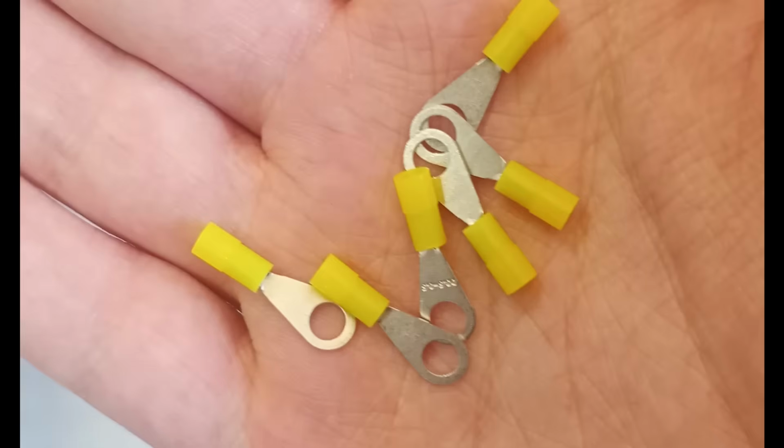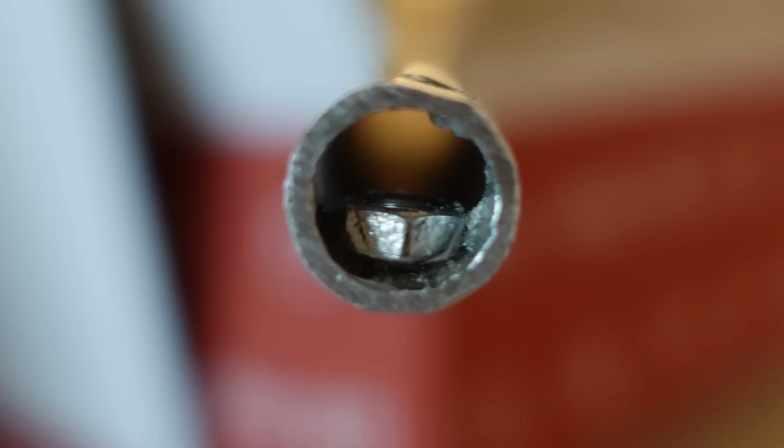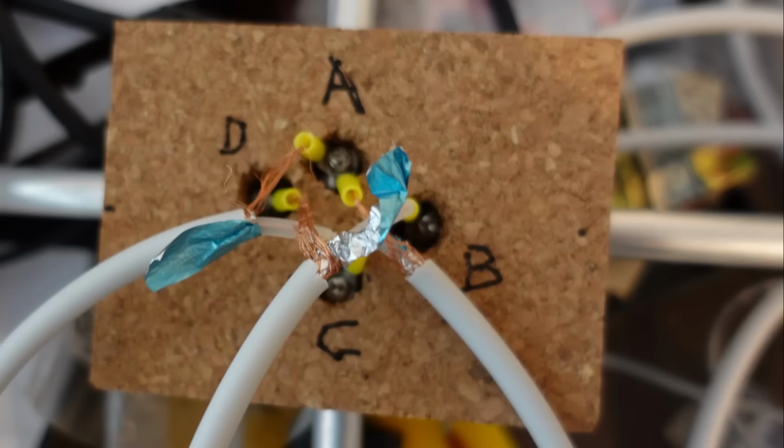I put some ring cable lugs on my delay line, as well as the cable that will go to my radio. As I can't access the tube from more than one side with this cork block, I glued some nuts to the inside of the antenna elements. I really should have tapped the holes, but oh well. I screwed on the terminals following the instructions, I think. The feed cable shield went to A, because I started with A, and the shield was the easiest one to move.